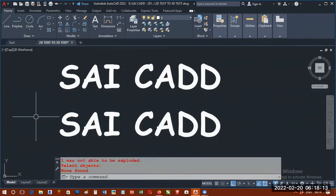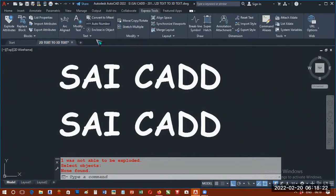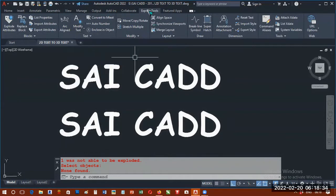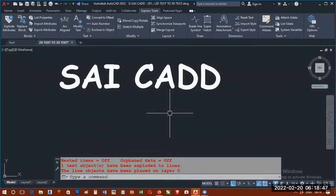So there is one more method where we can successfully explode the text. That is here in the Express Tools. Watch my cursor tip again. Express Tools, in the Text panel, go to Modify Text. In the drop down list, you click here and choose Explode. This is meant only to explode text. I repeat again: Express Tools, Text, Modify Text, Explode. Click there and select this word SAI CAD. Select this, enter. And now the text has vanished from that orientation.